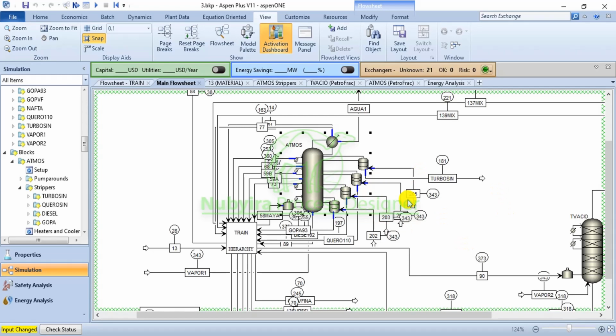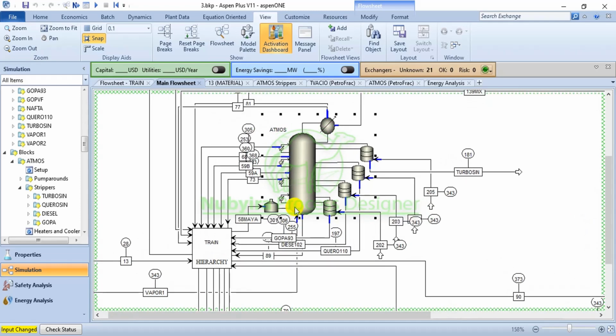Because the process cannot be changed, that is, the product temperature cannot be changed. I must get the product temperature from the specification. I must get the crude inlet temperature, that is, the furnace temperature that is coming out. The temperature of each of the pump around returns must be constant.